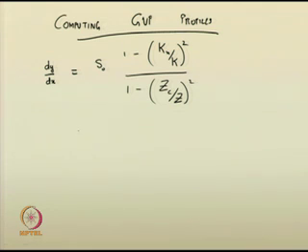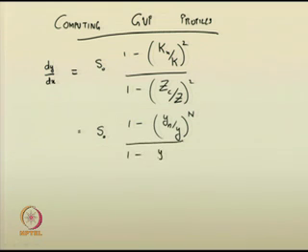This you can write in terms of y also, we have derived it in the last class: 1 minus (yn/y) to the power of the hydraulic exponent n, divided by 1 minus (yc/y) to the power of m.